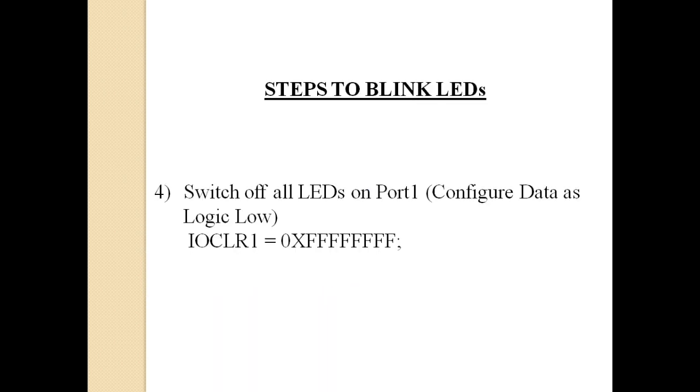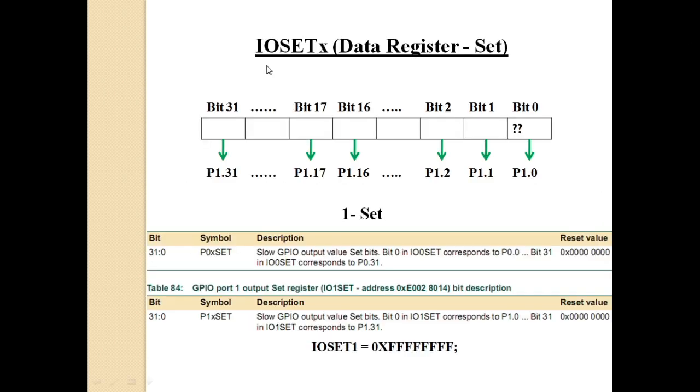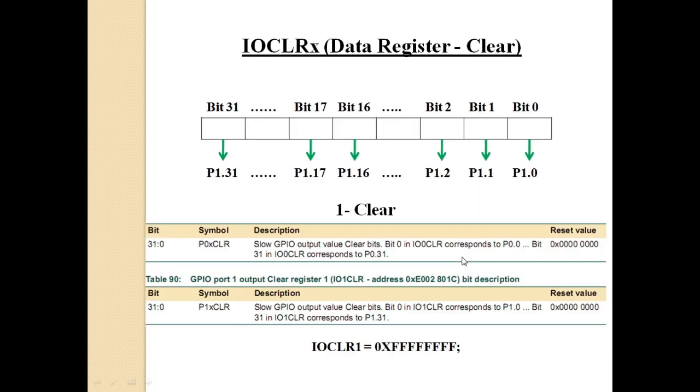So for setting the pins, you are using a special function register known as the IO set register. Similarly, for clearing a pin, meaning writing logic 0 to a pin, you have another SFR known as the IO clear register.